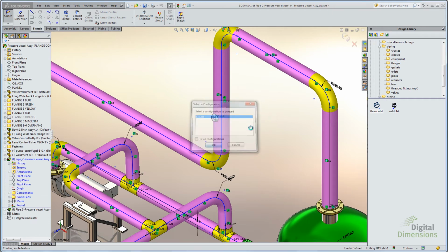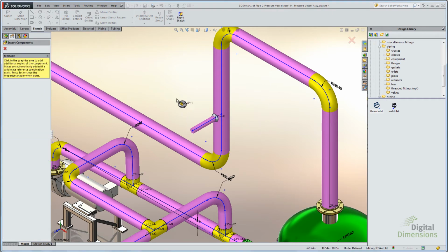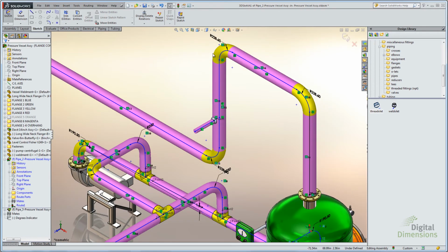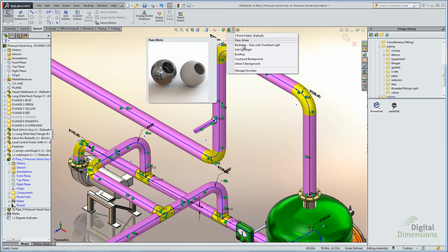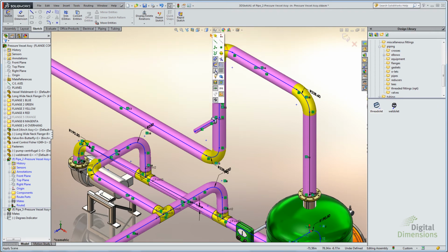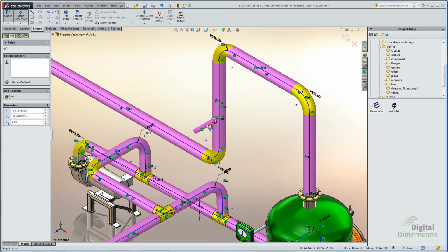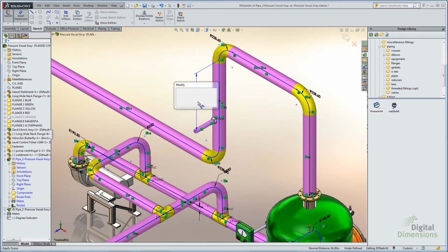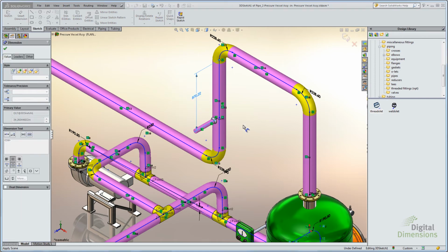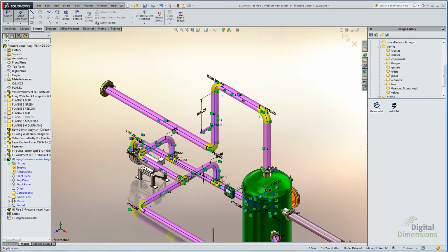And now when I first place it, before it wasn't very user-friendly. It was a little bit detached if you moved it around too much, and it wouldn't really work real well. But you can see here, if I turn on the sketch relations, it does have an along Z, a perpendicular relationship here. The nice thing now is I can add dimensions. In this case, I'll add a linear dimension to this one. So it's a lot more manageable than it was before, which is very nice.